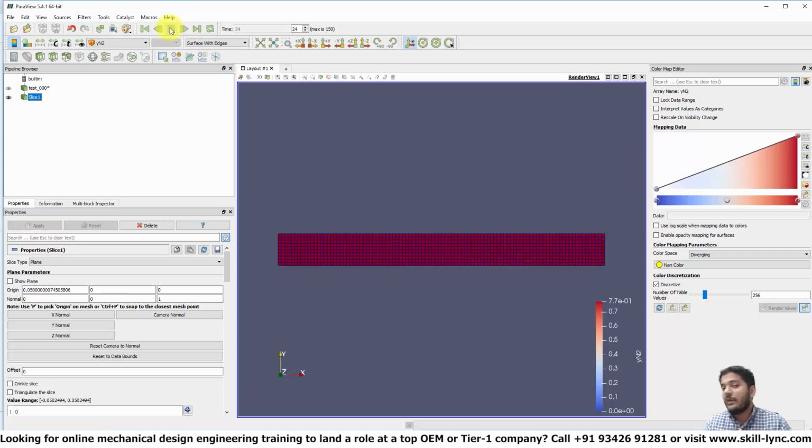So the whole reason why we are setting up a different initial condition is to show that initial condition in a continuous flow simulation doesn't matter. No matter what initial conditions you put, unless it's like super incorrect, the simulation is still going to take that data, it's going to just push it out. And eventually you will get the right results. And one thing that you need to do with a steady state simulation is you need to run it till a point where convergence is reached.